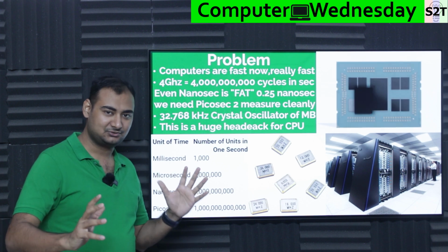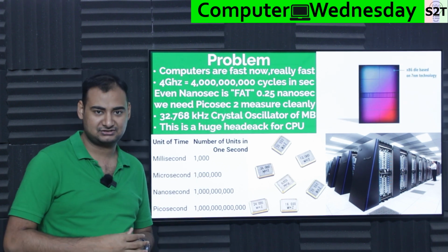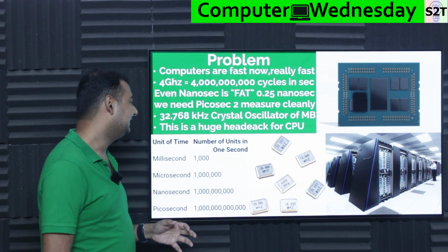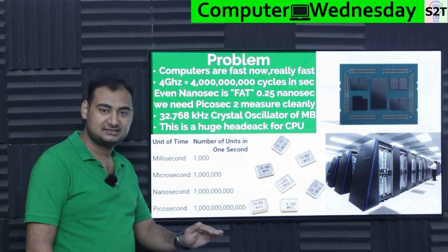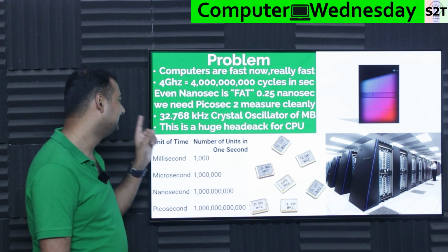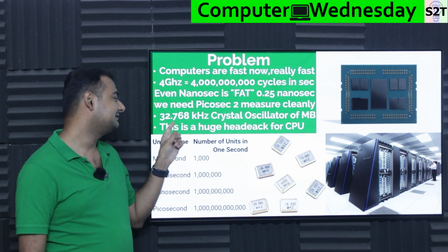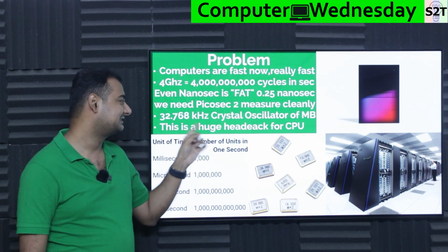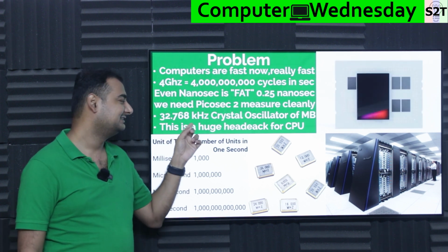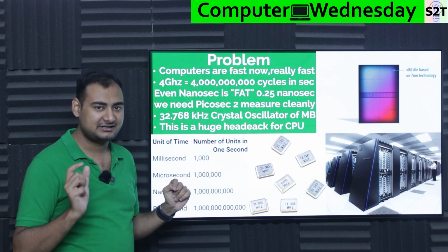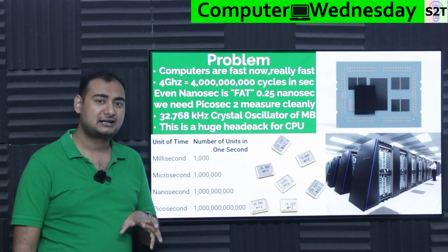You can have a motherboard with this GG amount of 4 gigahertz system, or maybe even 5 gigahertz, and the real-time clock it has, most likely, again not necessarily in our model, but most likely, will be a 32.768 kilohertz crystal oscillator for your clocks. Let that sink in. Gigahertz, kilohertz. And you may find better oscillators generally around the networking area.